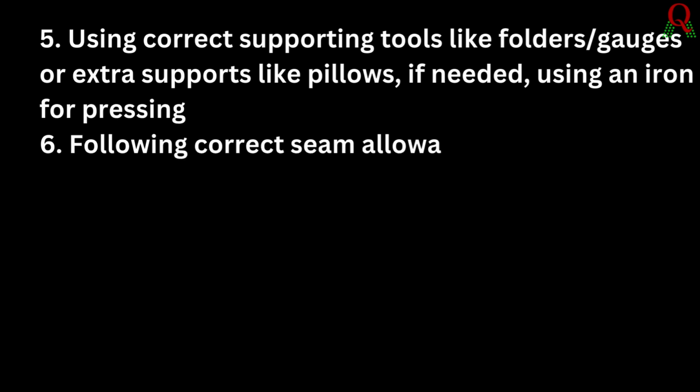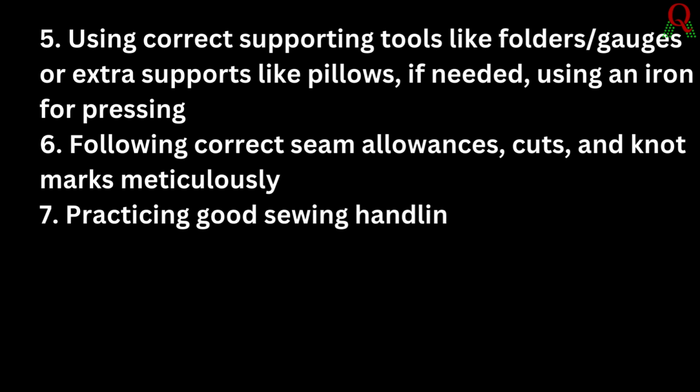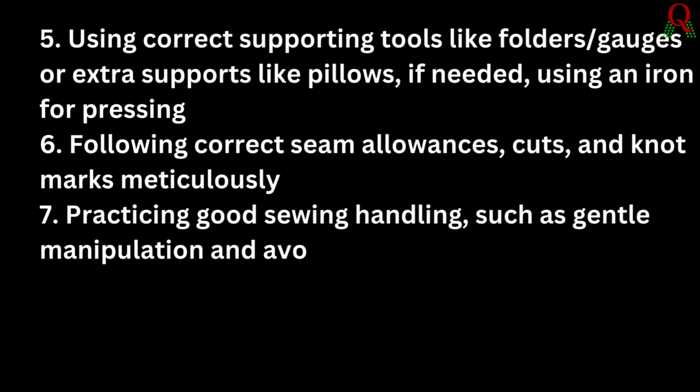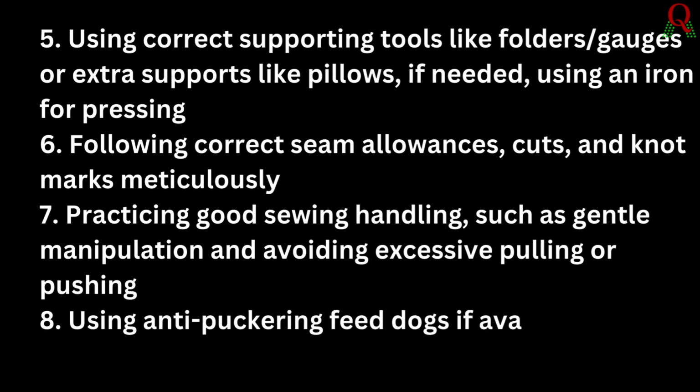Following correct seam allowances, cuts, and knot marks meticulously. Practicing good sewing handling, such as gentle manipulation and avoiding excessive pulling or pushing. Using anti-puckering feed dogs if available on the machine.